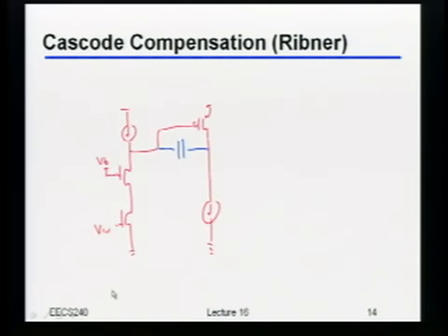Well, remember, a cascode device is kind of like a common gate amplifier, right? So his idea was, instead of putting the Miller comp cap where I drew it in blue, why don't we do this? In other words, why don't we take the CC from the output and tie it back into the source of the cascode there, rather than into the drain?